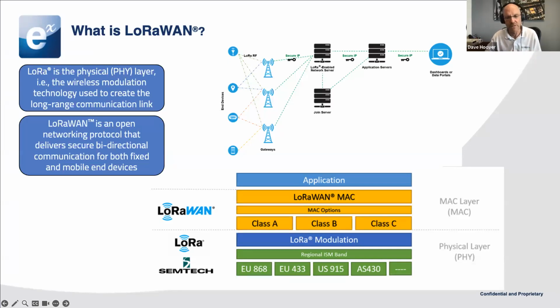But as soon as you want to have many devices connected up to the cloud and have the cloud communicating back to those devices, clearly you would want some way of standardizing that, right? How do you authenticate those devices? How do you provide security for those types of things? How do you join up to the server? Things like that need to be taken into consideration. How do you address the devices coming back down? All that is what LoRaWAN takes care of.